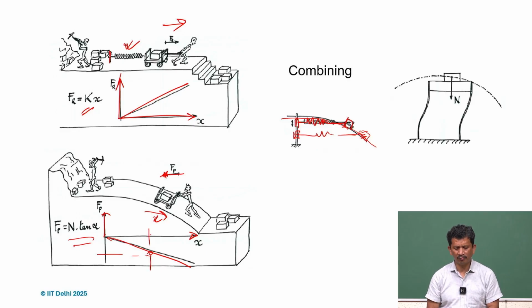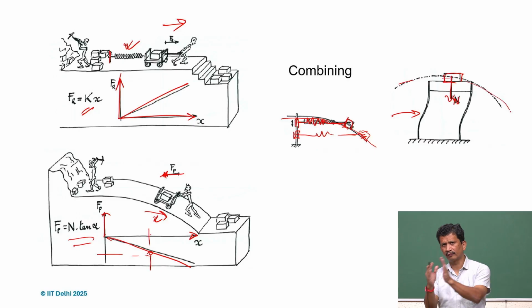In flexures, in compliant mechanisms, what is good is that the negative and the positive stiffness are intrinsic to the flexure. Because it's an elastic mechanism, the positive stiffness is already there. And with some arrangement, if we are able to get that negative part, so for instance in this case, if we apply a load N, and since it's moving in this kind of ramp, there is a negative aspect.